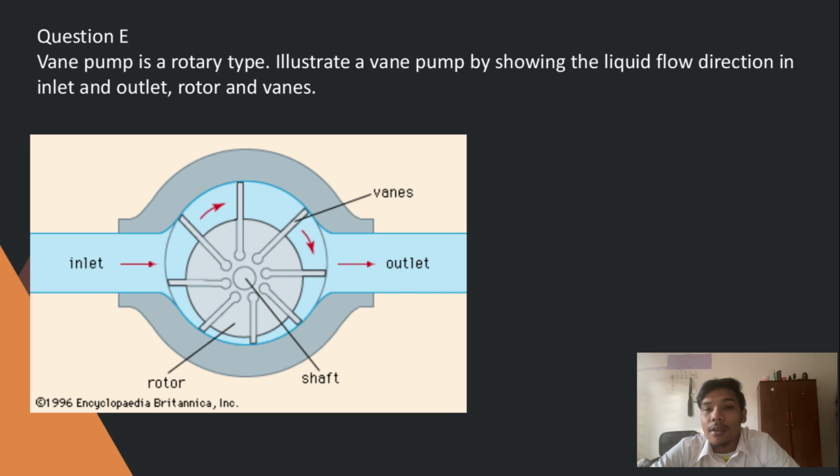Each rotor slot contains sliding vanes. As the rotor rotates, centrifugal force, hydraulic pressure and push rods work together to extend each vane to the casing wall. This creates an expanding cavity on the inlet side, creating a vacuum which pushes liquid into the pump.